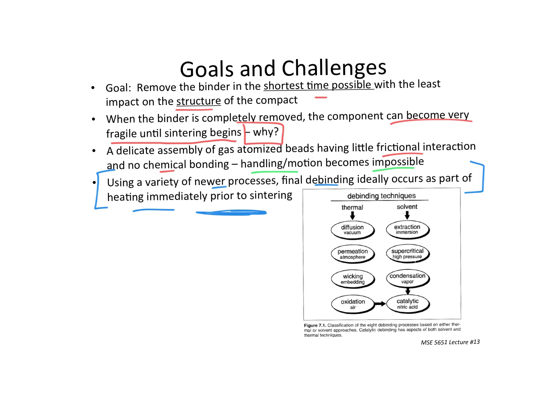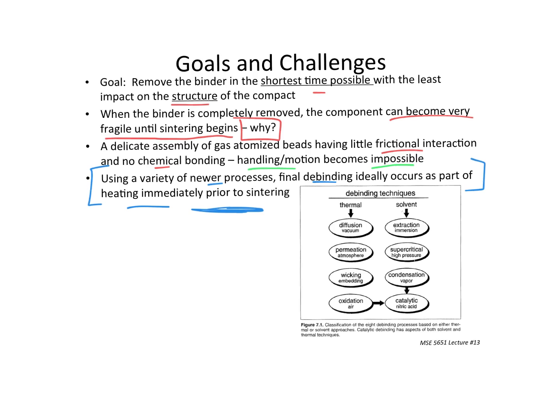And of course, then the strength goes way up. But until that sintering process begins and you start actually forming grain boundaries between these particles, you rely on that polymer to hold everything together for you. It could be the carbon breakdown products of polypropylene at that point, but it's still holding everything together, all right? And sintering kicks off.